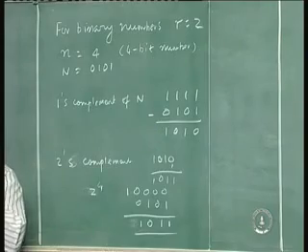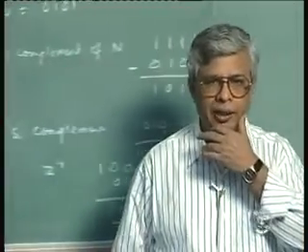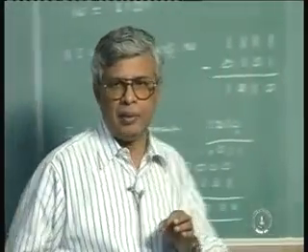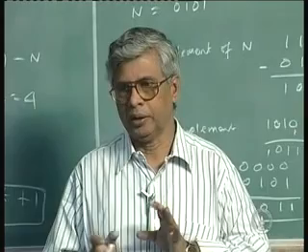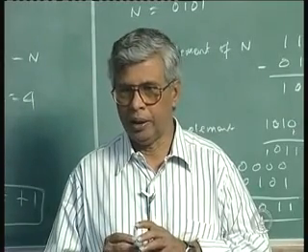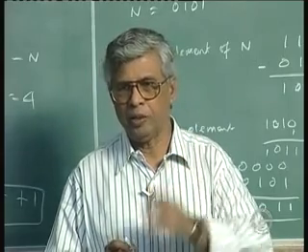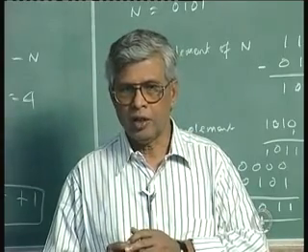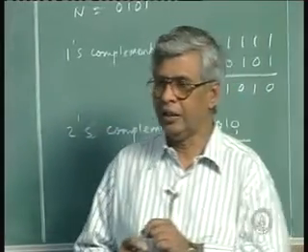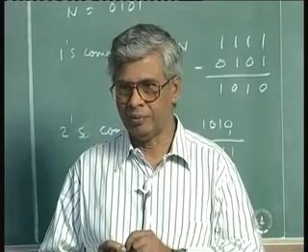Now, where does it fit in the case of subtraction? Subtraction is the same as adding the complement of that number. Suppose I want to subtract b from a, a minus b. Instead of designing a logic for subtraction, I can use an adder logic and add, instead of b, the complement of b.